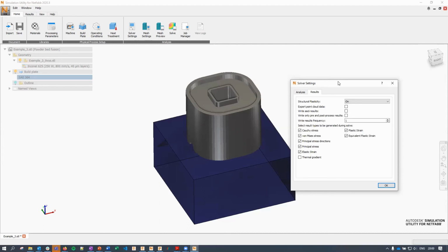If this concept is too novel and foreign for you, simply think of it as: are you interested in understanding the residual stresses that this part would go through after print? If yes, you need to select this to be on. If no, keep it off. We have this option because keeping it on and calculating it means a little bit more time. And in case you're not interested, then you can keep it off. For the sake of this demo, let's keep it off.